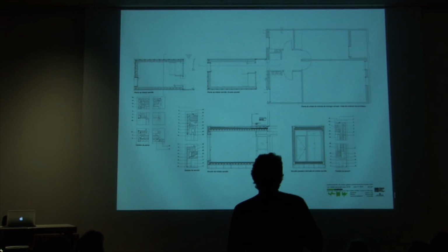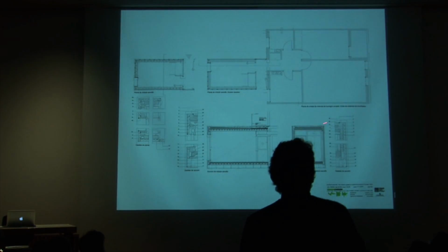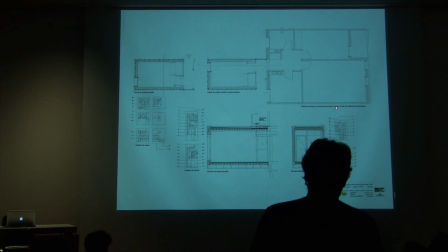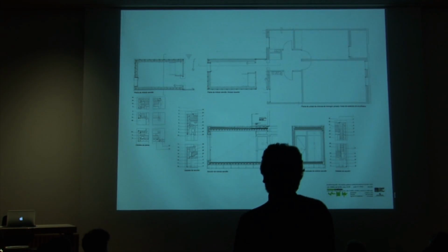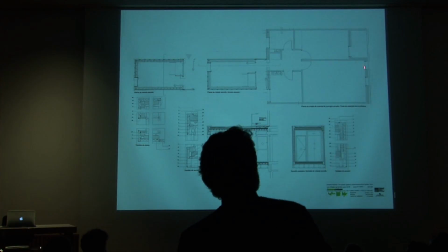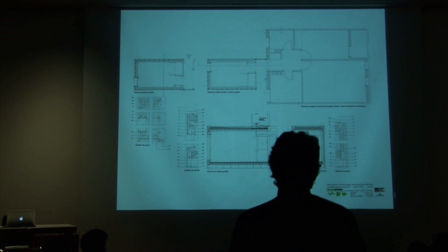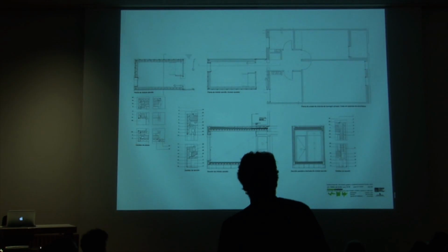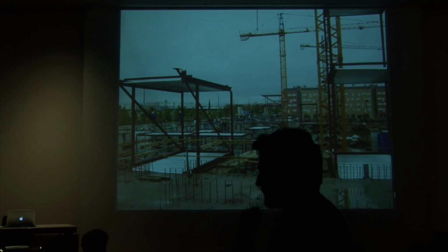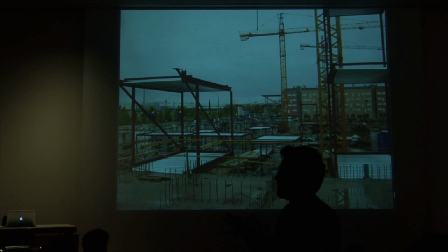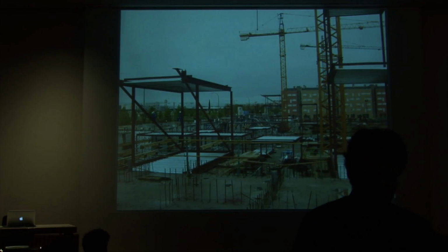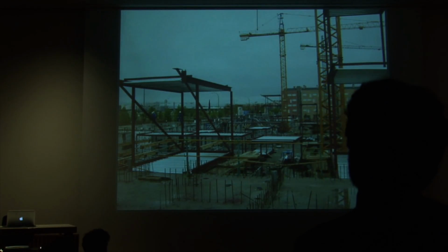The structure was very interesting because the concrete part of the building had no columns, so all the walls are mechanical structure. They are 10 centimeters. There is nothing thicker than 10 centimeters concrete. And on the facades, we have a double wall with isolation in between. And the other part of the project is lighter, is made out of these steel skeletons that were built on site, and they were raised up with those cranes and placed on the final position, and then casted together with the concrete monolithic structure.